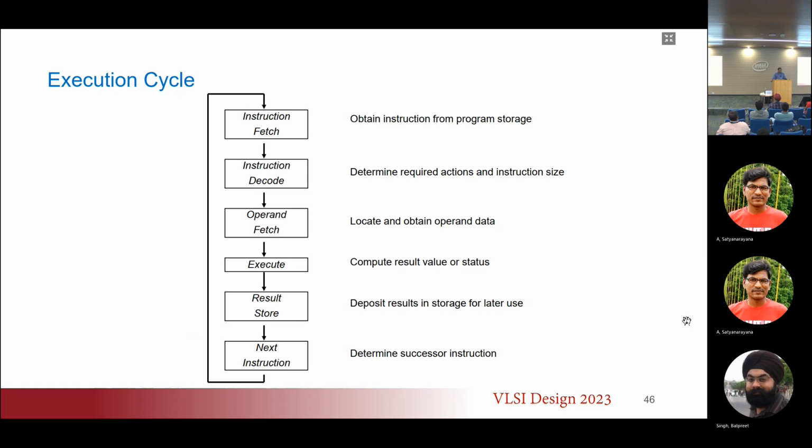If you look at the same thing being done by a systolic array, there are no instructions. There is basically a hardware unit where you put the data, and then every clock cycle you just simply cycle through, and every processing element does multiply and accumulate, and I'll show you the hardware.